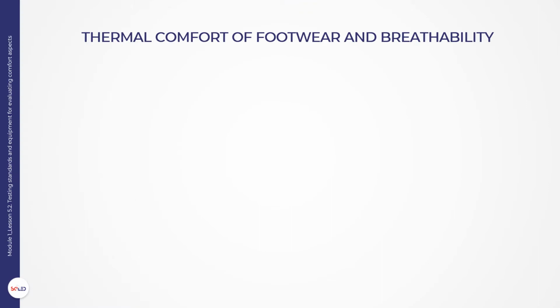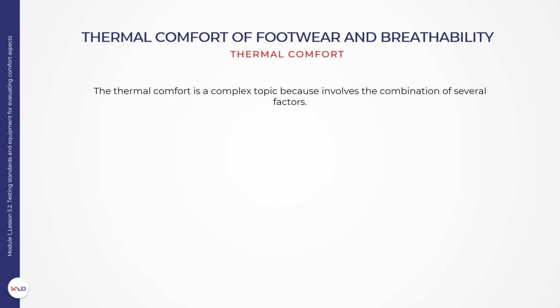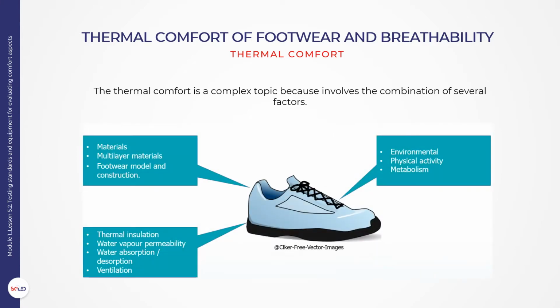Thermal comfort of footwear and breathability. Thermal comfort is a complex topic because it involves the combination of several factors, including the materials used for footwear and their properties, such as water vapor permeability, water absorption and desorption capacity, and thermal insulation. For example, thermal insulating materials will minimize the heat loss from the inside to the outside of the shoe, and breathable materials will promote the elimination of sweat to the outside of the shoe.